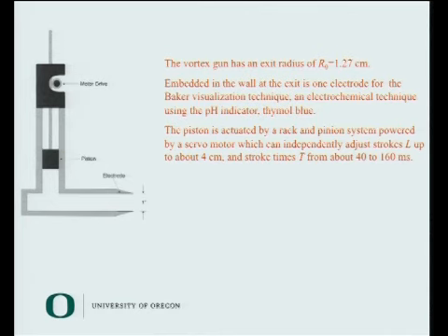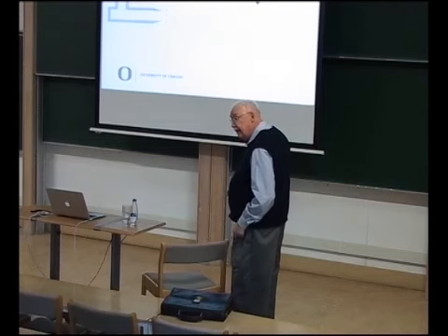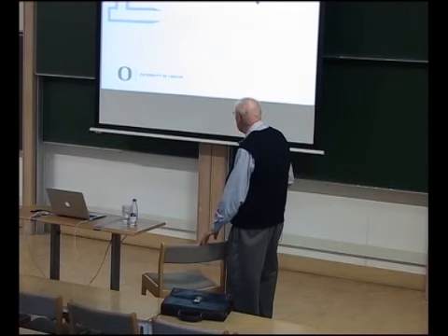The piston here is operated by a rack and pinion, and a motor drives this small gear and pushes the piston down as accurately as we can with linear velocity. Of course, it's really a trapezoidal waveform because you have to accelerate, you have to decelerate.